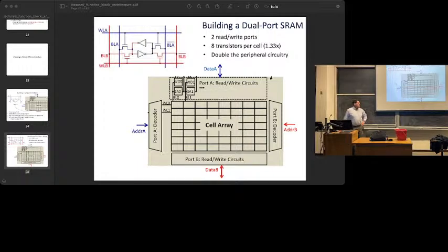Yeah, that's a good question. So most FPGA RAMs are built out of what's called a true dual port core. Okay, so that's what I've shown you here, where both ports can do read or write. And that's the most common way you design an FPGA RAM. It does make the electrical design of the RAM cell a little more tricky, to sort of guarantee it's stable even if you do 2 reads and stuff like that.